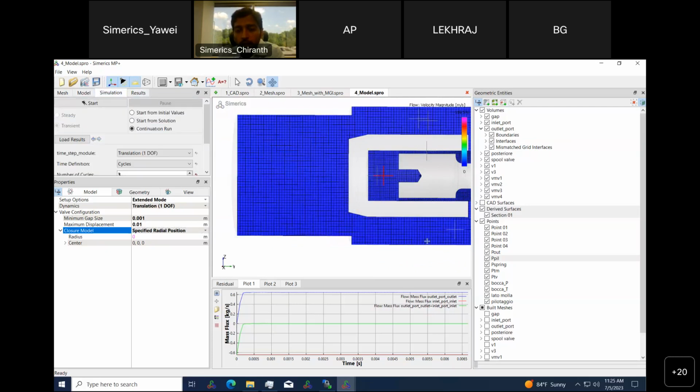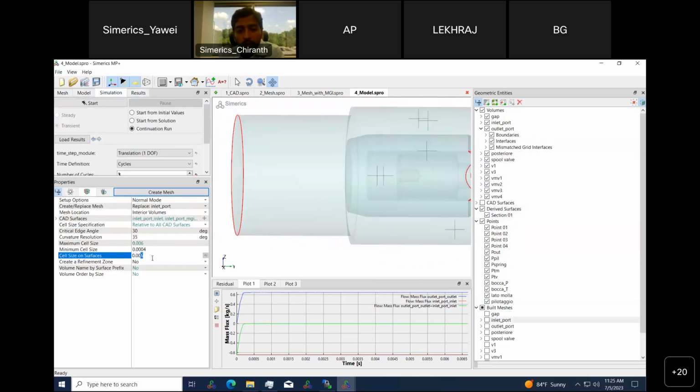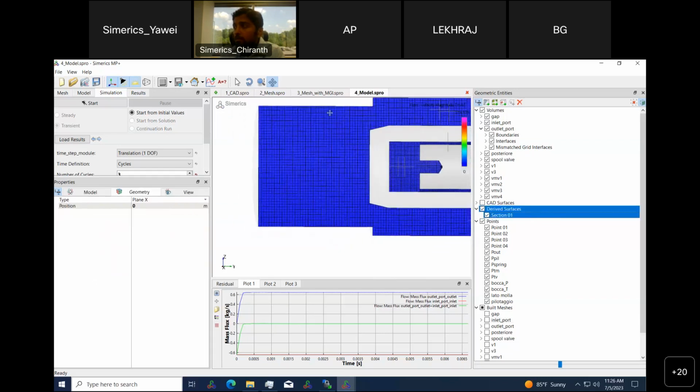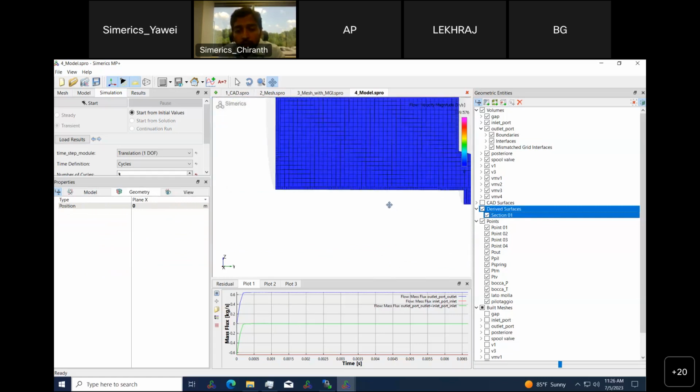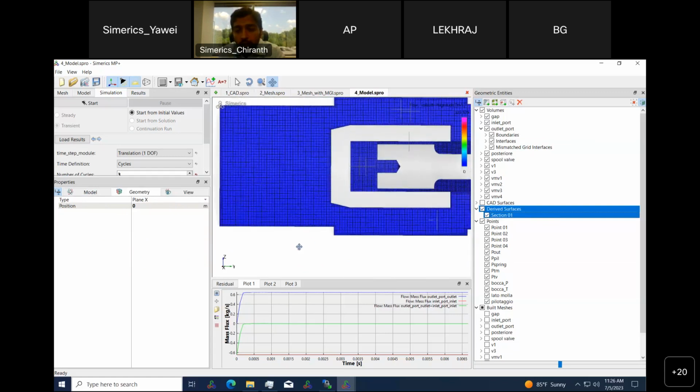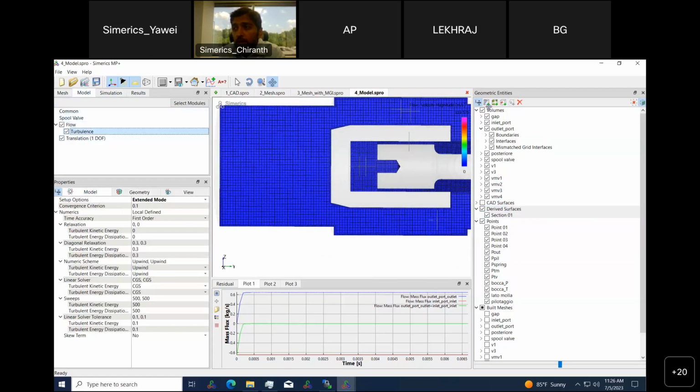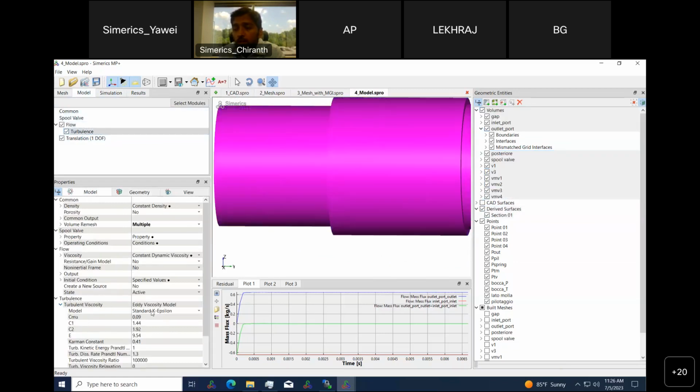And I think one thing, so we have done a lot of different cases, and what we have noticed is the way turbulence wall models are modeled with respect to how your meshing works, as well as how your solver solves for it with the different parameters, is of utmost importance when you talk about turbulence models. We have the K epsilon model. That's what we have. We are implementing a few other models which will be in the versions that will be coming out later this year or early next year. But so far we have not faced a lot of issues in terms of getting good fidelity of results even with just our boundary layer refinement.